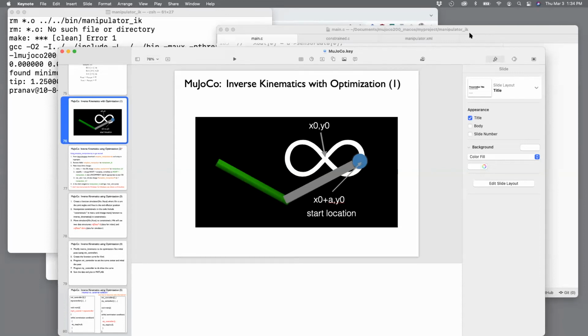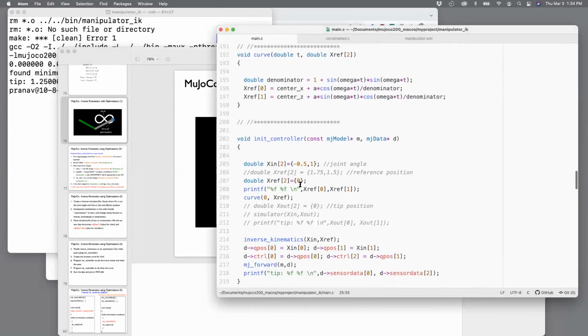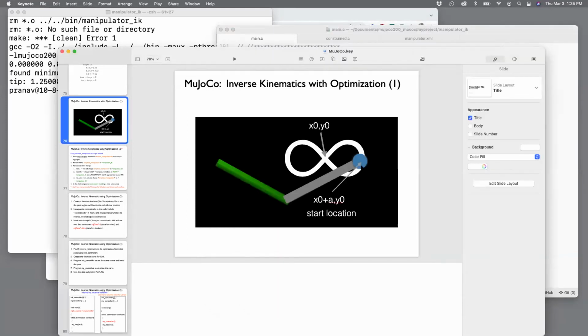This is where I put these angles and I propagate it through the system. It predictably puts the manipulator here. I will use that sensor position to put the center at a distance of a to the left. That's all I'm trying to do. So let's do that. And that's just one of many ways of setting up the initial condition.